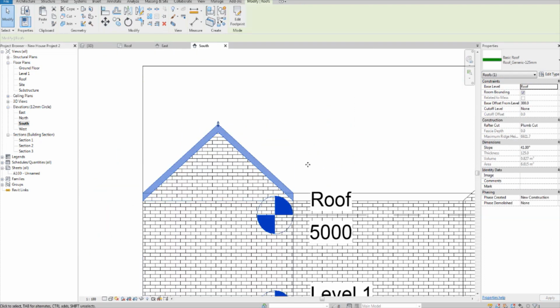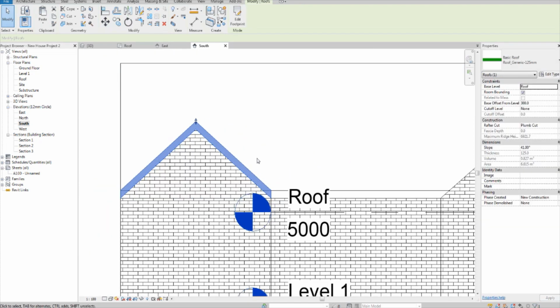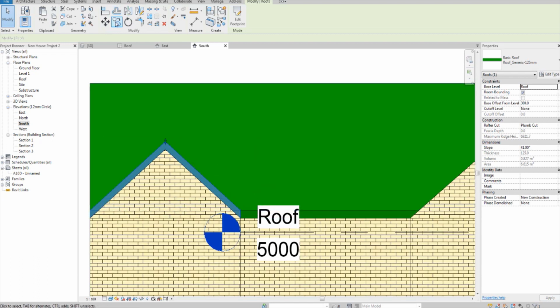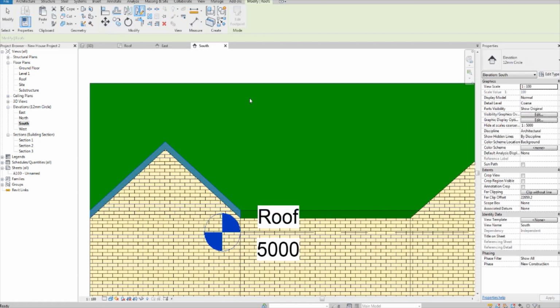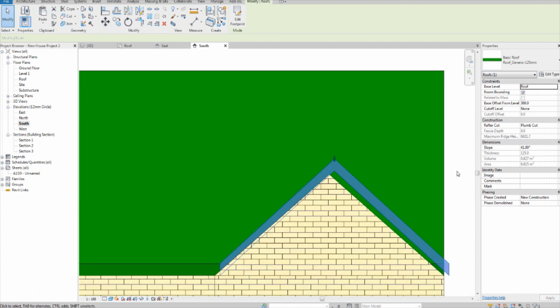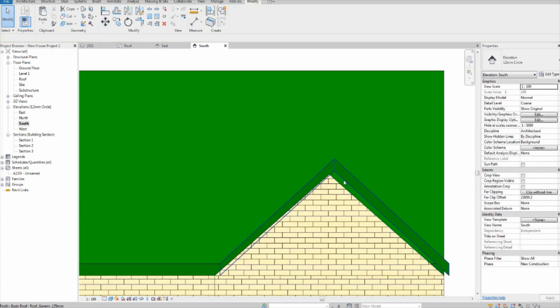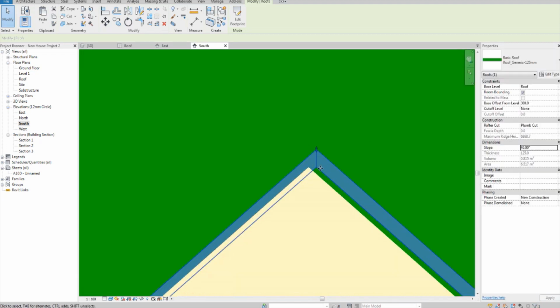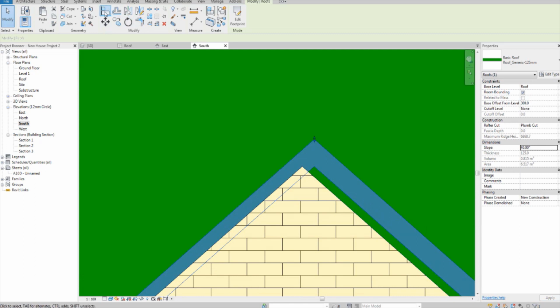Well, I'll show you what it looks like when you have to copy one over and edit it. Although I showed you already. But let's do it. So I'm going to mirror this exactly there, and it's not fitting. So I'll select that roof and in the properties turn the slope into 40, and then I can just align.